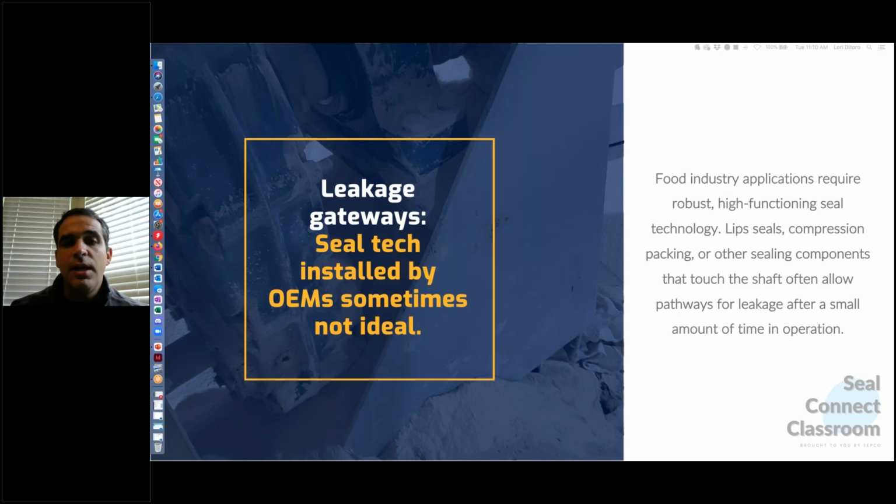Now, the wear on the shaft that is created by friction cannot be improved over time without upgrading the shaft with either a sleeve or just replacing the shaft altogether, which gets expensive, creates downtime, and creates an endless cycle of maintenance and cleaning. And that's where the air seal comes in, with non-contact technology that won't wear the equipment. So that cycle is broken.